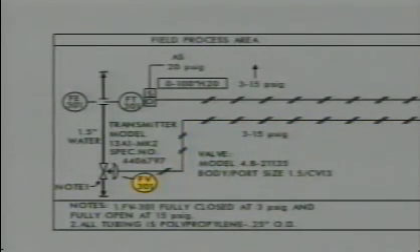The controller signal operates valve FV301. This is a globe valve with a diaphragm actuator. When the valve receives the signal from the controller, it adjusts the rate of flow in the system to maintain it at the required set point. With the flow rate adjusted, the process starts all over again.